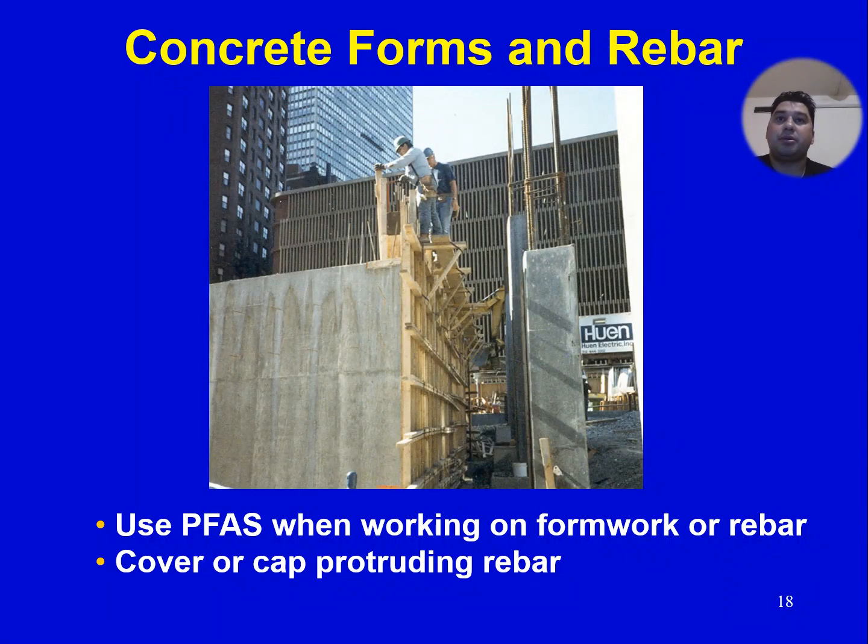Concrete forms and rebar. Use a personal fall arrest system when working on formwork or rebar. So in these places, you should use the personal fall arrest system when you are working. Cover or cap protruding rebar. So these also need to be covered.